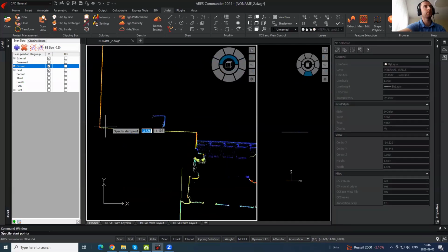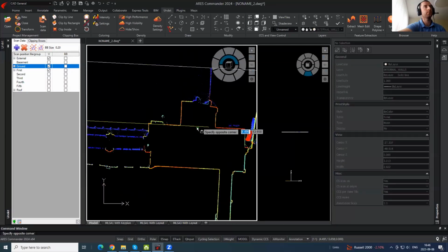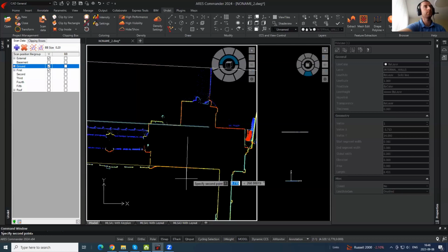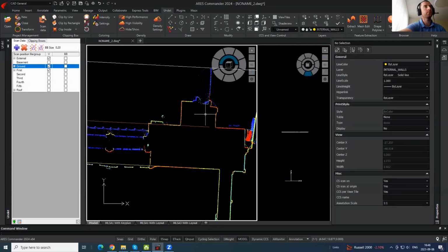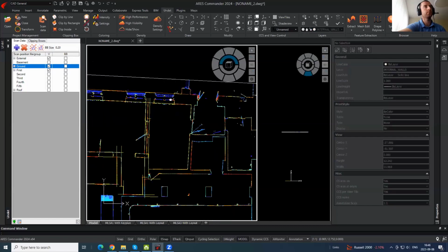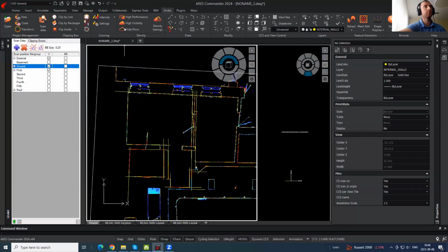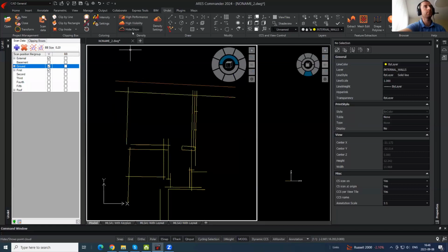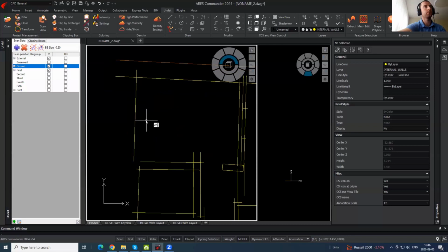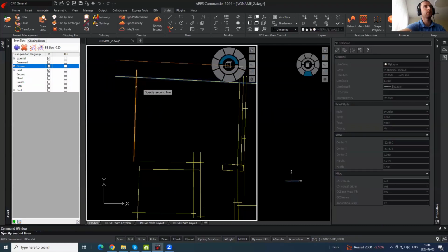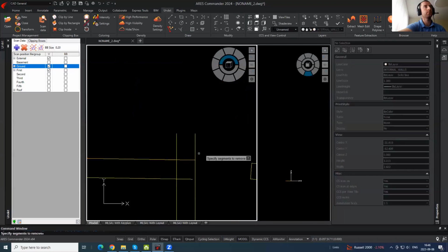Also, the external part should be parallel too. This will go to the external walls layer, and okay, let's see what we have. We have some lines, but now we have to trim corners. We can use the chamfer command, I guess, but we can also simply trim.